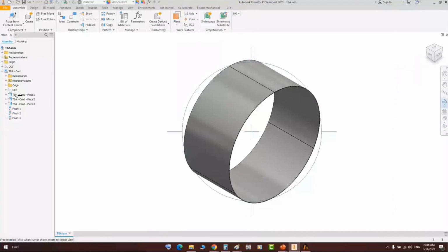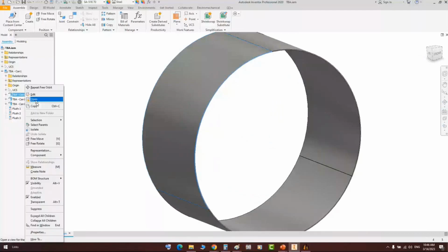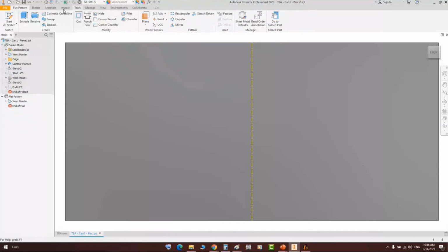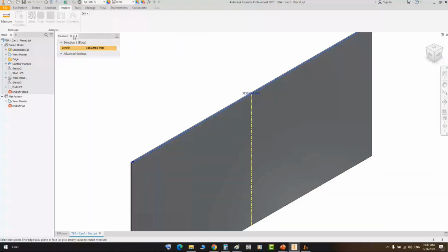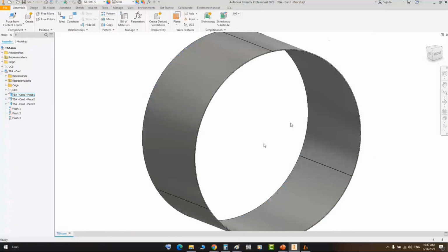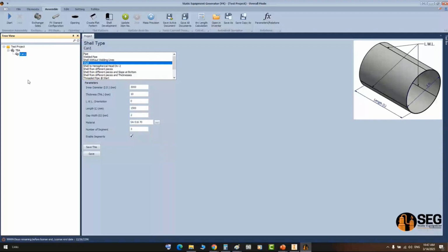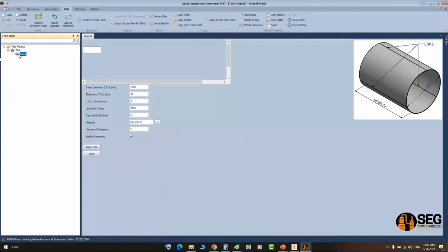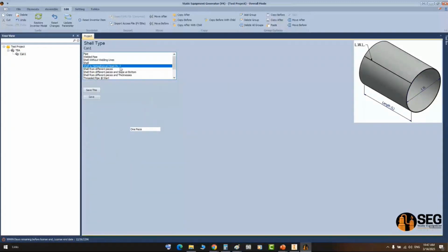That's the first part. Here, if we open it, they are all equal. So when you generate the sheet metal development and get the length of this one, you will get an equal length for all blades. That's the development length of the blade, which gives you 3 equal blades on this shell course. Now let's check another option for the shell. From elements, let's reset the Inventor model and go to another type of shell, which is a shell to a hemispherical head with negative straight flange.